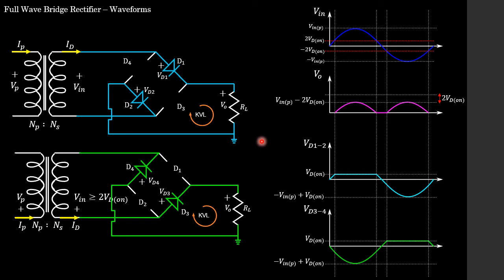And also to note, students, that the frequency of the output for our full wave rectifier is 2 times that of the input voltage. At the input voltage, we can see the time it takes to complete one cycle, and it ends there. So that is the period of our input.